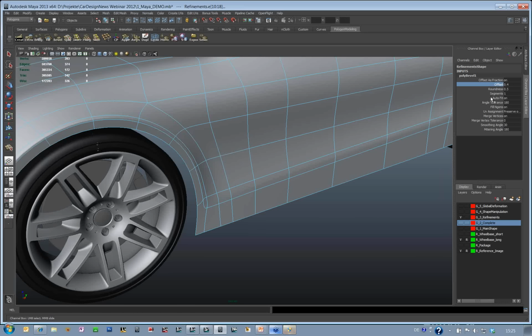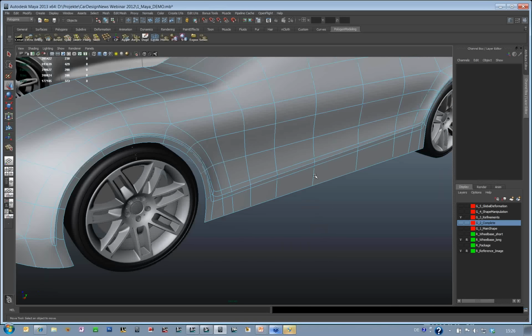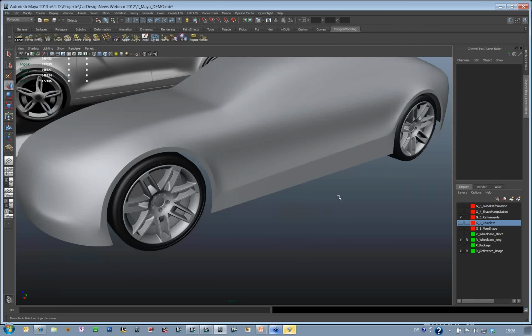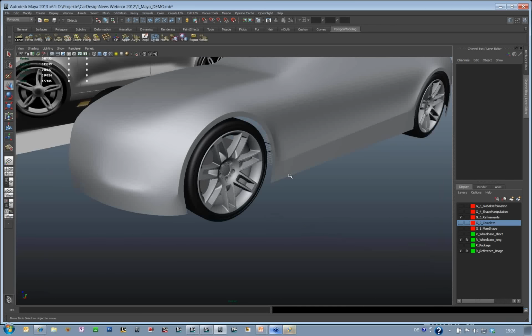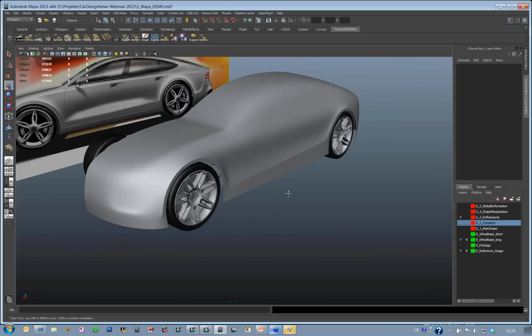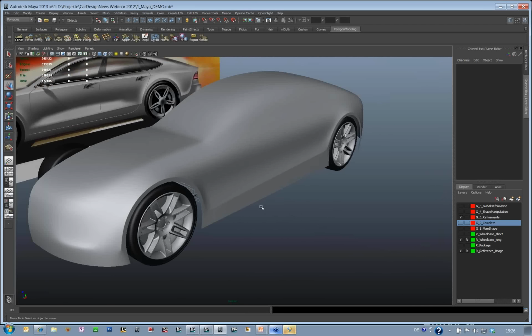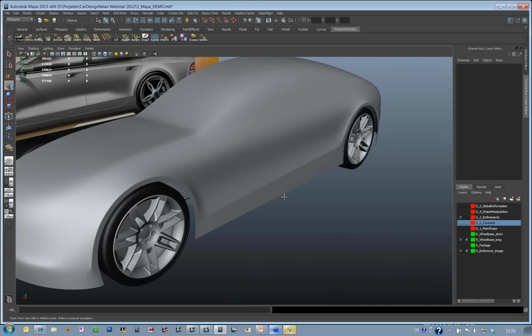So it's a basic principle and works very reliably in all of the tasks. But at the moment, I'm not completely satisfied with the sharpness. It's a little bit too flat. So I can add, for example, a segment. I can increase the density in this place by adding the additional segment, and you see now what kind of effect it has. It brings a really sharp, crispy edge and defines the side part of the car very straight. That's the first example.